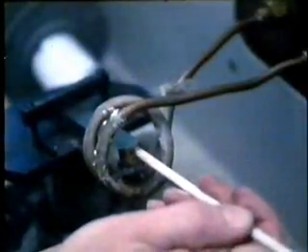The tungsten carbide layer is responsible for the toughness and resilience, particularly during shock loading, while the polycrystalline diamond layer gives better tool performance. Due to this random polycrystalline structure, the tools have uniform properties in all directions, and there are no problems of orientation. Each tool has identical properties.